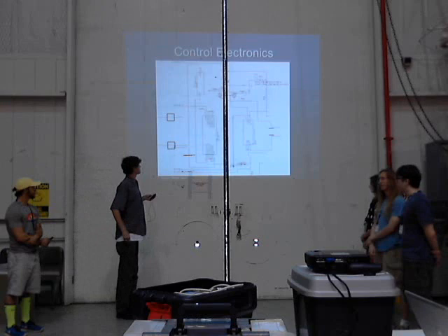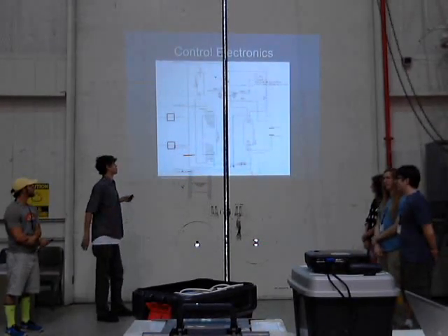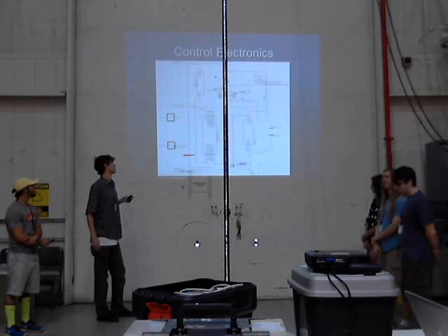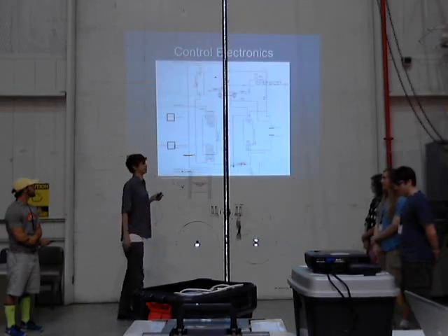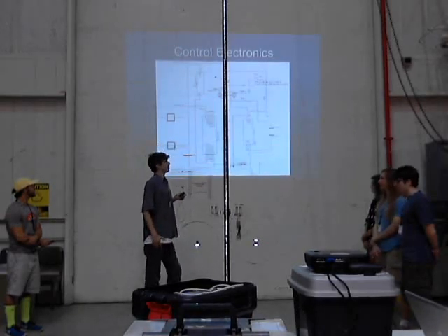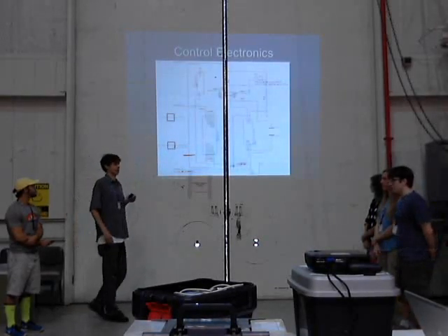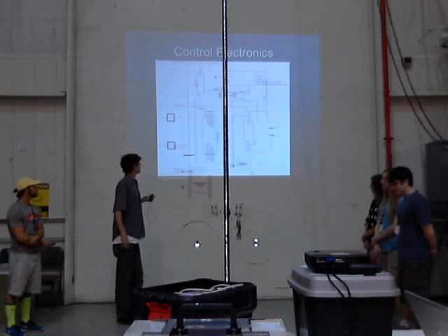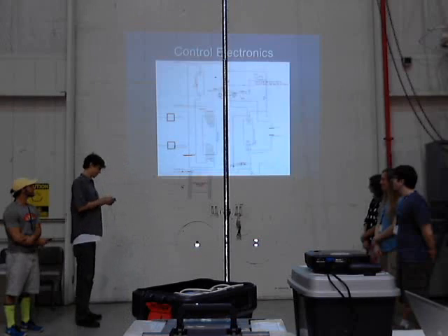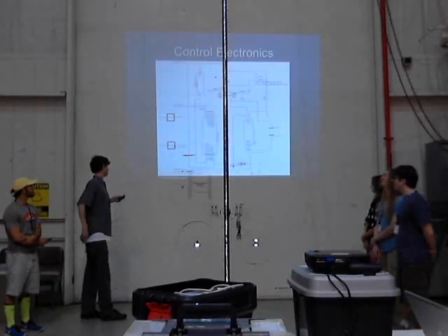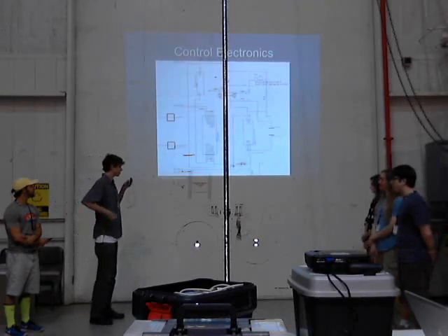We anticipate, depending on the op amp, typically between 5 and as high as 20, but on average 10 femtoamps of leakage. At 8 femtoamps, we anticipate approximately a 10% error in measurement. So it's fairly adequate. Our voltage divider and our signal. In our signal conditioning,